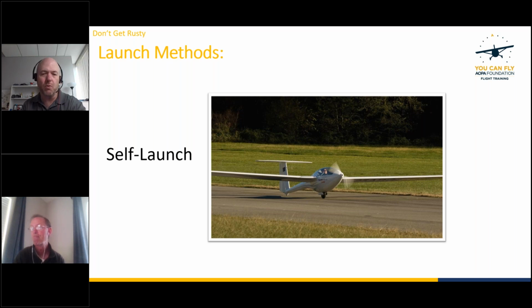Is this one too? Because obviously they have just the one main gear. Do you have to have a wing runner when you're doing the self-launch like this? No, you have a wingtip wheel. So I'll just take off with one wing on the ground, and once I get going, I've got enough aileron authority to lift the wing. Interesting enough, just the motor torque will also help me lift one of the wings.